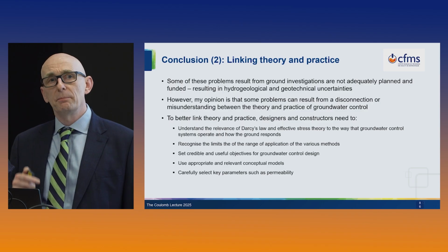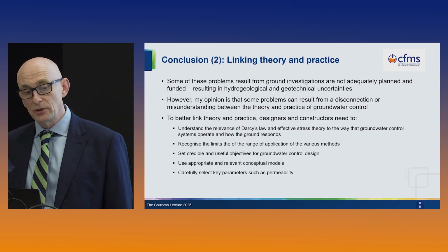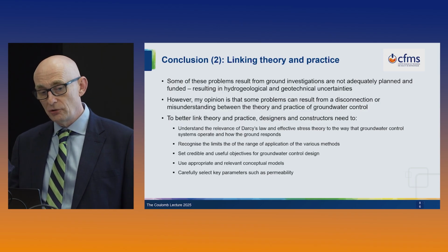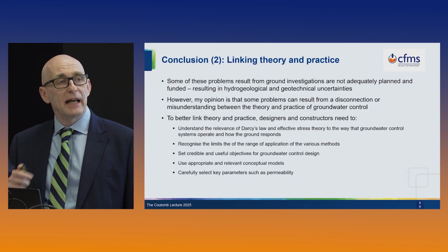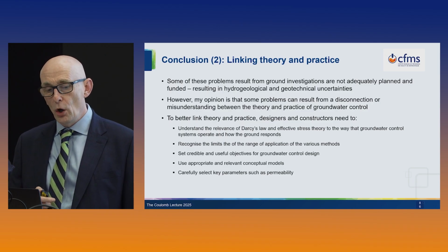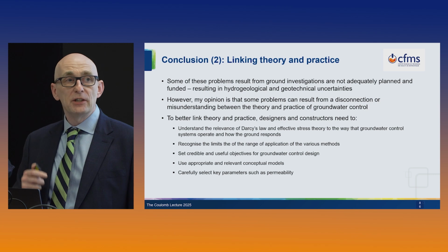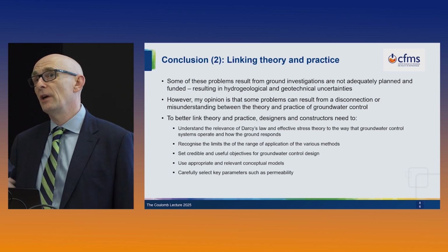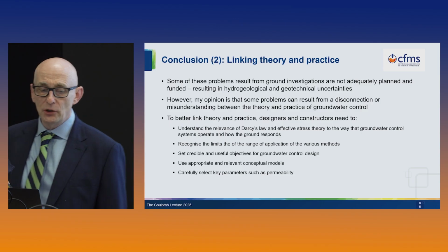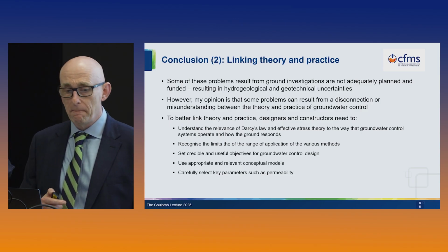And I think to better link theory and practice, designers and constructors need to understand the relevance of Darcy's law and effective stress theory, and understand how the way we manipulate hydraulic gradients affects the way that the ground responds. We need to recognise that each of the different groundwater control methods have different ranges of application, and we should apply those carefully. We need to set credible and useful objectives for ground control design.